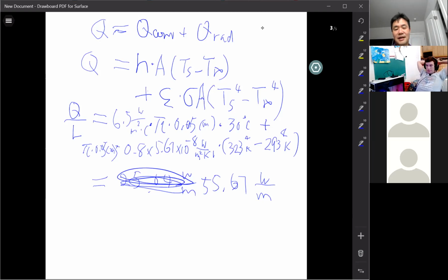Look at them separately, and then you should be able to solve those problems. Each of conduction, convection, radiation has separate equations. Then just list the equations, see which letter is your unknown, which letter you don't know. Then one equation you can find one unknown, right? So I think the key is to separate into the separate mechanisms for a comprehensive problem.